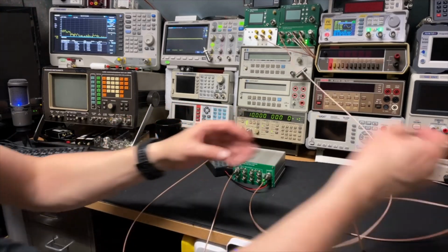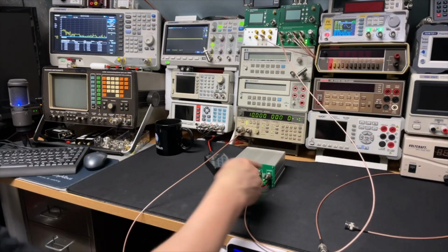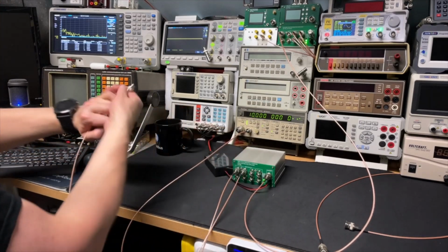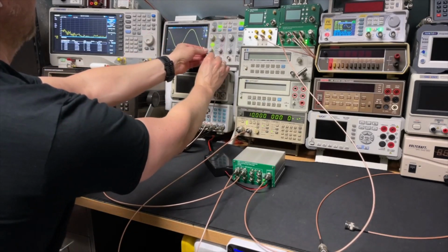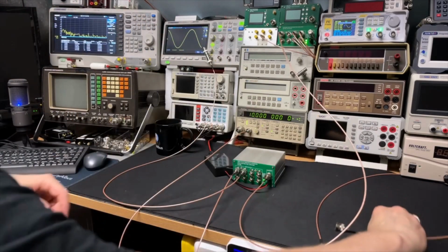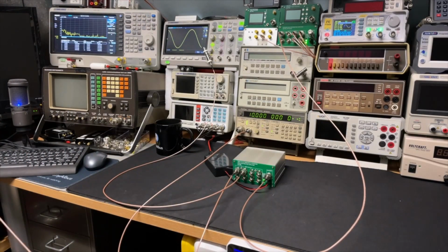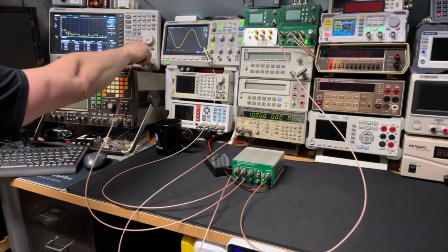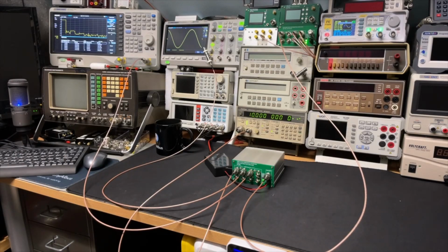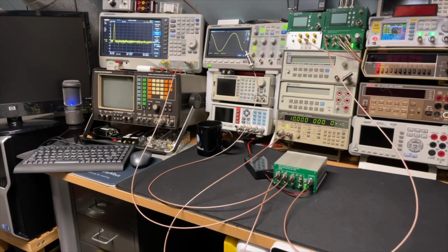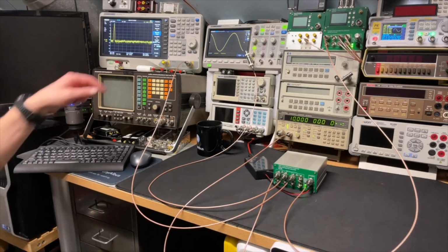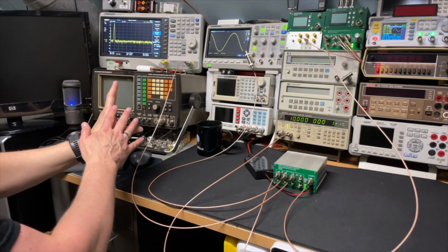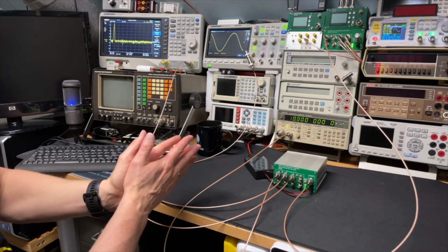But what does it look like? Because we are on the input, we put a square. But we saw with the bandpass filter, it becomes a sine. Do we have the same here? Yes, we have. What does it look like on the spectrum analyzer? Well, exactly the same. Super clean. Well, on the spectrum analyzer, you can see it is again very clean. So it is the same. It is like the other distribution amplifier, but then with the bandpass filter.